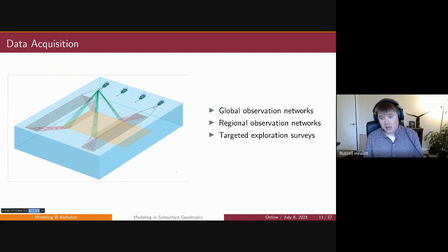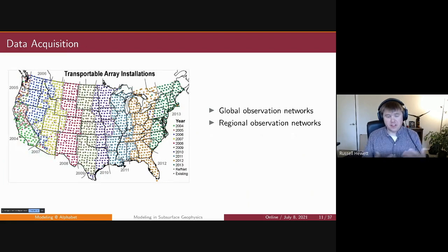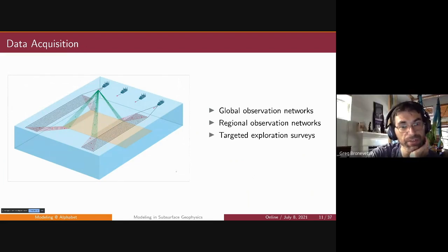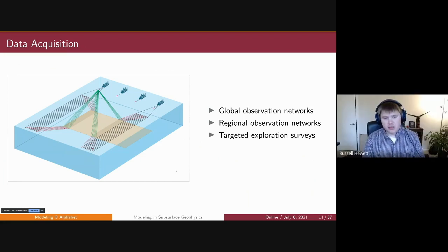Well, obviously, we're not going to get 360 degrees from this, but you can significantly increase the azimuth of the survey by moving things around. With the fixed surveys here, largely you're relying on earthquakes, which are distributed differently. So you're getting that azimuth, hopefully, by having a good distribution of earthquakes. But here you're controlling the structure itself. Okay, so the value is the different angles here, not the same. It's never the same measurement twice, even for fixed ones. Correct. It's not the same measurement twice. Though sometimes it can be, and that's used just to increase signal to noise.